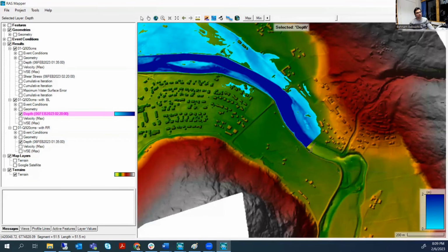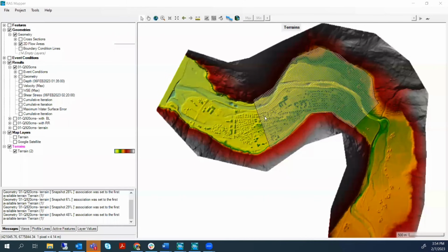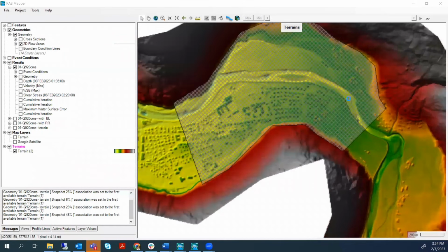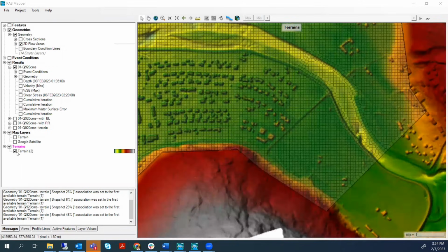And then try to refine the center line of your river, then the bottom of the banks, and then the top of the banks, and then introduce the accurate flow data and run your model and enjoy your modeling.